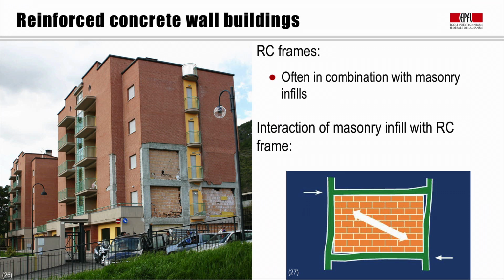So reinforced concrete frames are often filled with masonry. One calls this masonry infills. And the interaction of frames and infills is really rather complex. So you can see here on the left an example of a building that has again been damaged during the L'Aquila earthquake. And you can see that the cladding has fallen off, and actually also part of the masonry infills have fallen out. So these infills consisted here of 2 layers of masonry, and the outer layer has fallen out.